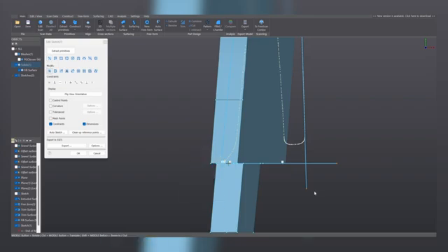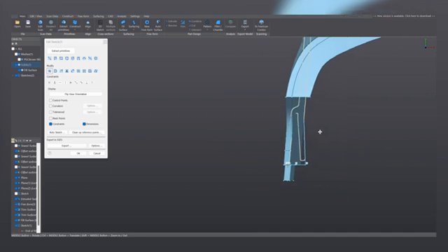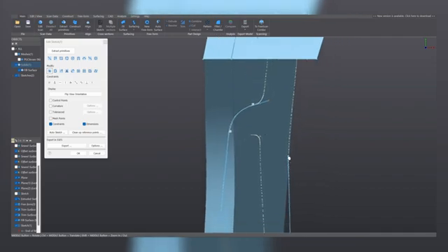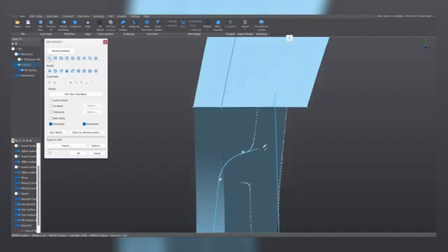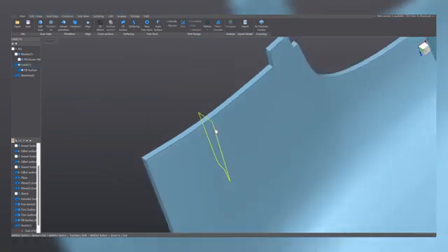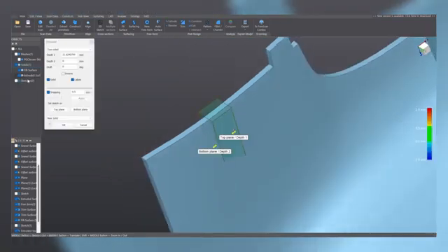And let's now join these endpoints. Now on this side, we are going to draw a small line following this angle here. And we join these endpoints, and we even do the filleting. And now we can extend these lines a little bit more and connect them together. That's it. Click on OK. And now we have a closed sketch that we can extrude and obtain a solid.